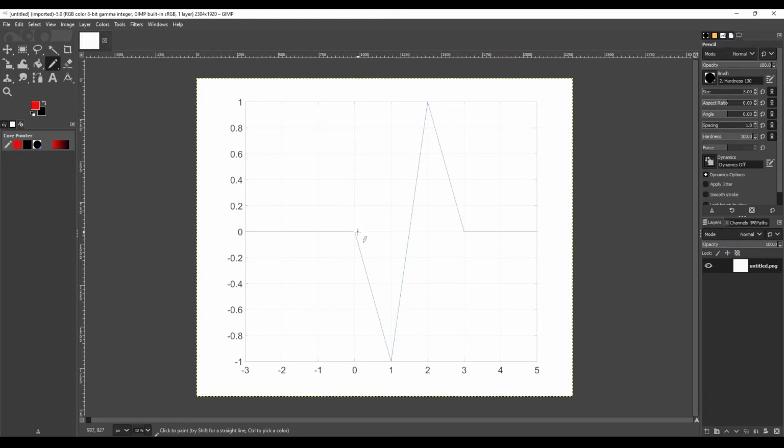In this video, we're going to see how to generate this shape in MATLAB, and in the process, we'll learn how the Sawtooth function in MATLAB works. You cannot generate this shape directly using the Sawtooth function. We need to follow some steps and make some tweaks. The Sawtooth function actually generates continuous waves, so we cannot have zeros here. The value of y cannot be 0 here. So first of all, let me show you.